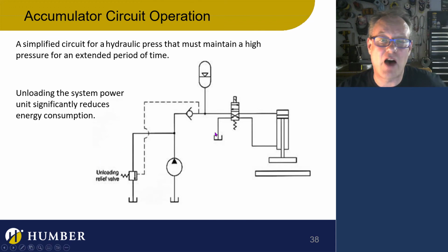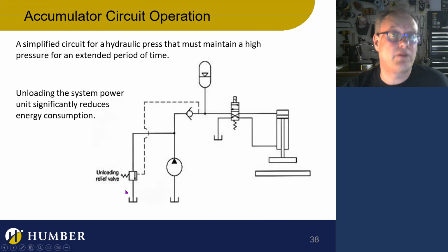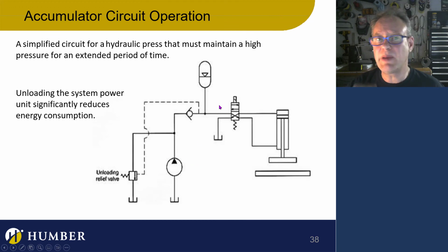So the unloading valve itself is going to sense the pressure on this side. It's going to then open this up, and the fluid from the motor is just going to go whoop, right down, right out to the tank. It's going to give the motor a break. That will happen when a hydraulic press or an actuator is working really, really hard. It has to work really hard, and you're stressing your motor.